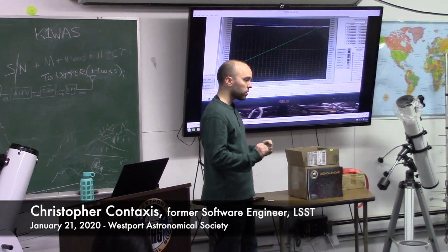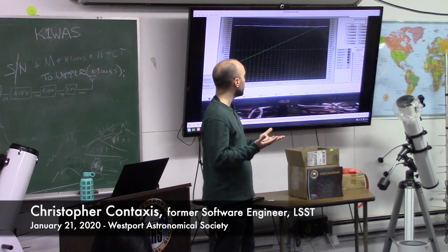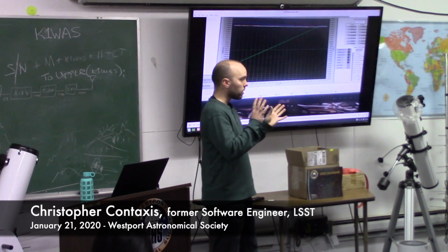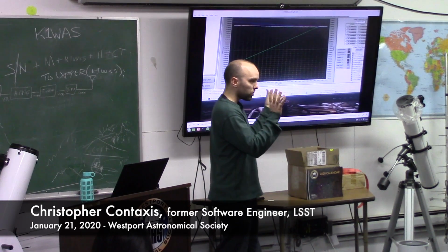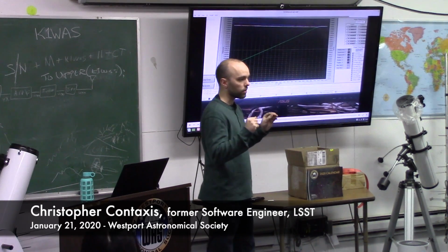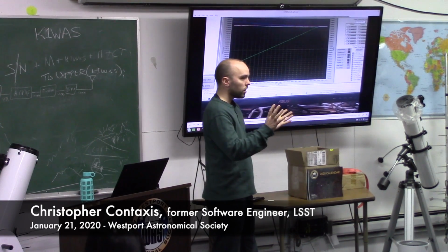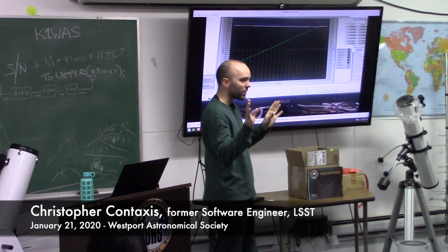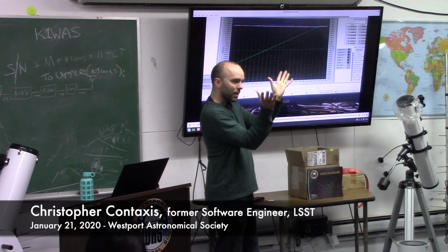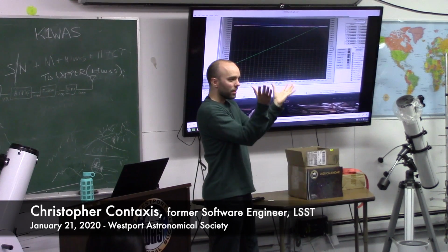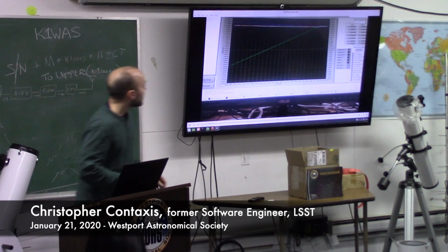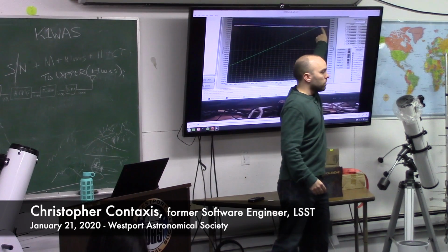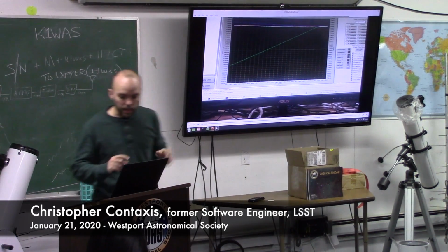Because the static supports, while you're slowly incrementing the amount of force that you're using to raise the mirror, are actually still pushing on the mirror. That pushing also puts little twists and turns, moments and other things, into the mirror. All that is captured here by these sensors; the mirror is twisting a little bit, a really small amount. It's not coming up straight up. It might come up at a slight angle until, as it does a little dance, and then once it reaches the reference point, you can see all of them come to basically 0, 0, 0, our origin position. So they snap in at that last moment.